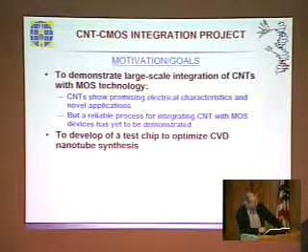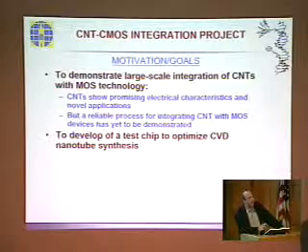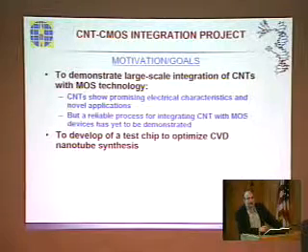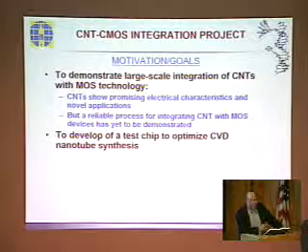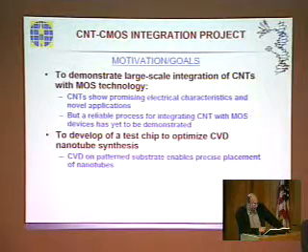We picked as a circuit vehicle a test chip which would allow us to use an NMOS switching array to simultaneously grow carbon nanotubes at thousands of sites on a chip. And basically what this chip is, is 2,000 carbon nanotube experiments on a single chip. And we use the silicon NMOS transistor tree to act as the switch that allows us to individually switch and measure as many as 2,000 individual carbon nanotube devices on a single chip.